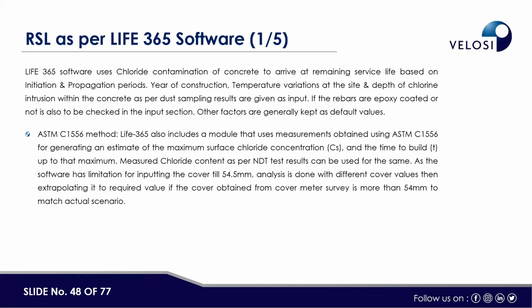The chloride concentration is given as a percentage of weight of concrete or percentage weight of cement. So we have these 2 value inputs, and we use them with the corresponding depth increments. We feed them into the software and do the assessment. One limitation of this Life 365 software is related to the cover, since as part of the assessment we also get the chloride cover.